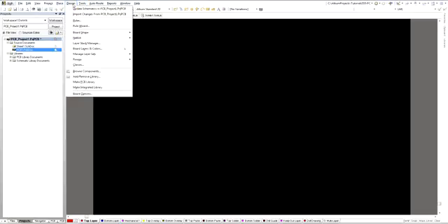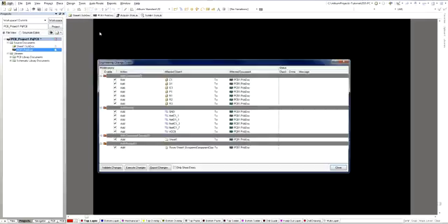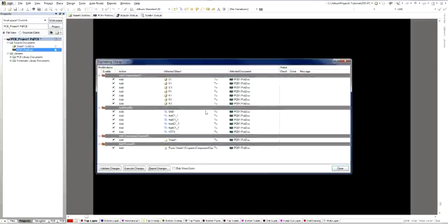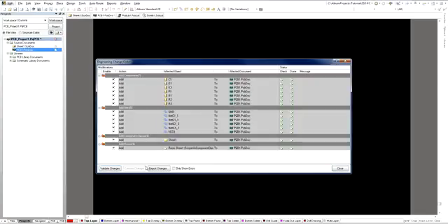And what we're going to do now is go into design, import all of your changes, and here you're going to see a list of your components as well as your nets, and you're going to validate the changes first. You should see check marks appear on the right side of each component and net, and this makes sure that all your connections are correct and all your annotations are correct in the schematic. If they're not check marks, make sure to read the warning signs, and you should see messages appear on the right. So what we're going to do now is execute all the changes.